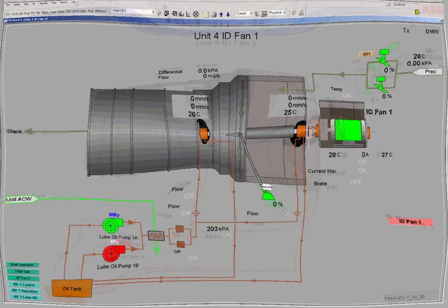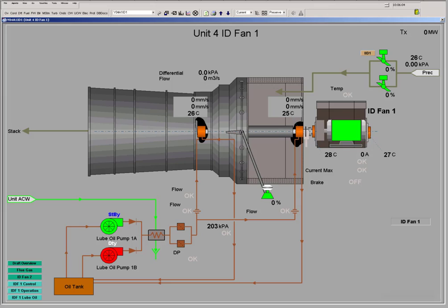Let's jump ahead to the 35-second mark when the motor start is initiated. Notice that the motor current surges and temporarily exceeds its maximum threshold, but it quickly settles back to a value below 200 amps, and the startup sequence continues. At 45 seconds the inlet dampers begin to open. Once fully open, the sequence is complete, and the control box displays in solid pink.